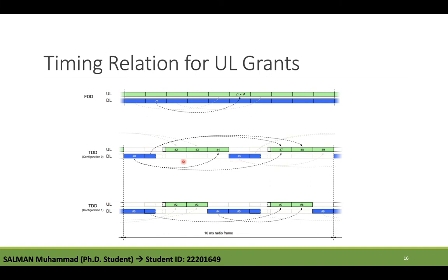Similarly, as in the downlink case, the uplink scheduler can exploit information about the channel condition, buffer status, and priority of different data flows. And if some form of interference coordination is employed, then also the interference situation in the neighboring cells. The channel dependent scheduling, which is used for the downlink, can be used for the uplink as well.